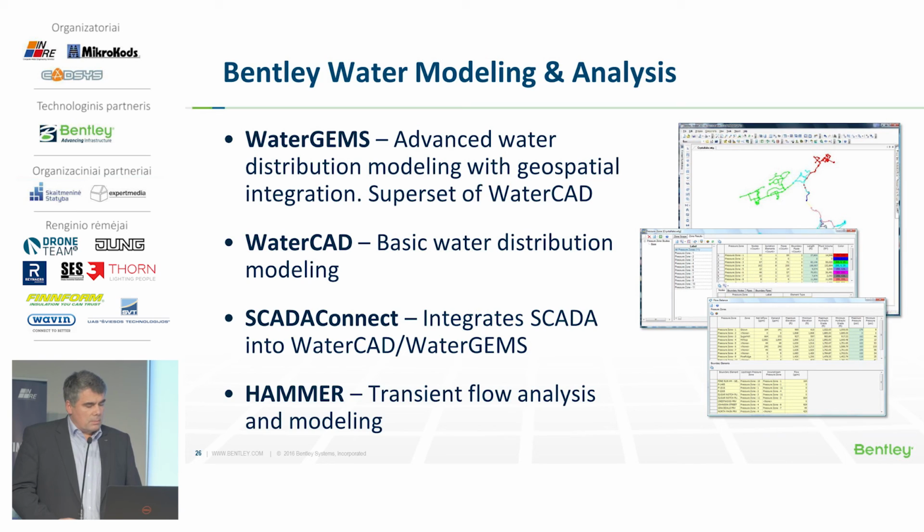WaterGEMS, which includes much more functionality, including some analytical things, some network modeling and optimization of existing networks, which is kind of a superset of WaterCAD, and includes besides that other specific packages for particular tasks like connection to the SCADA, because for instance, if you would like to calculate where the leakage happened in your system, meaning where the pipe is losing the water, you can calculate it much more precisely if you know the real-time, up-to-date data from the network.